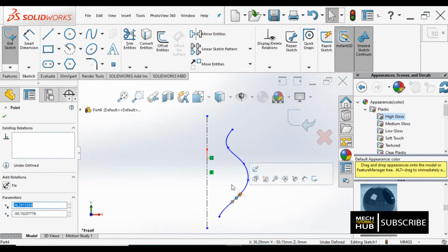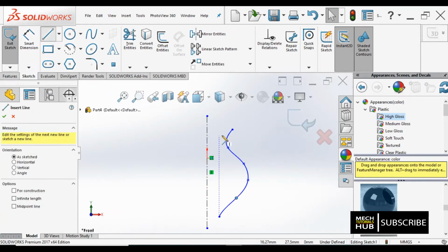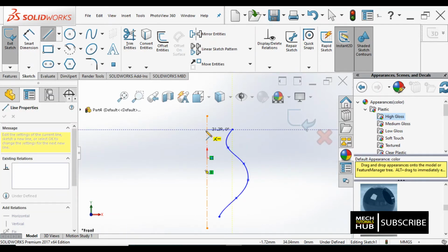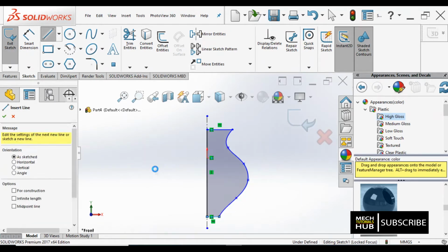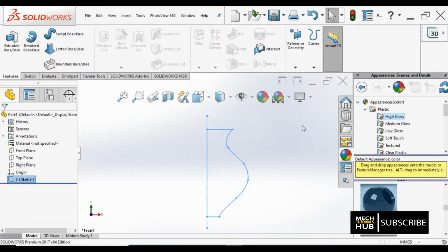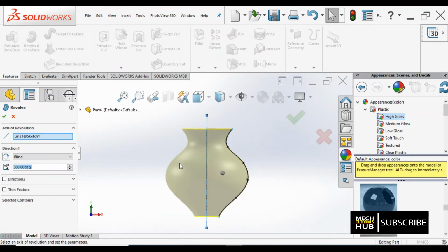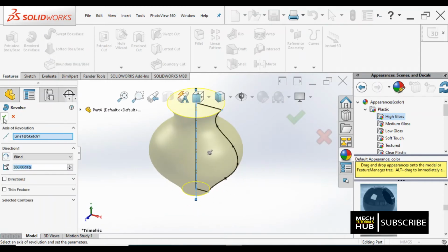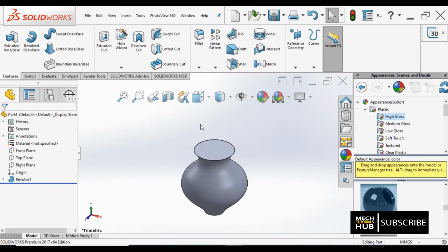Yes, got it. Let me control with these points so that it will help me out. Let me close the object, because it needs to be closed to rotate in case of a 3D model. Let me exit the sketch mode once you're done with your sketch. This is how the component looks.